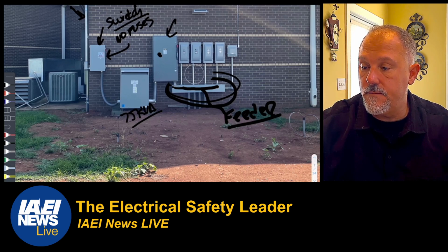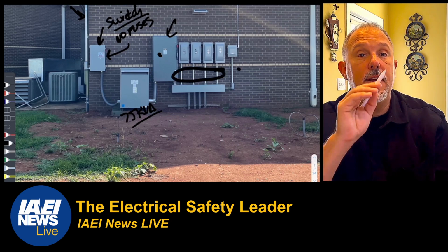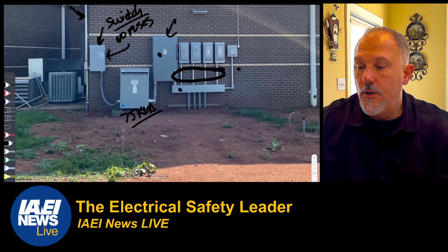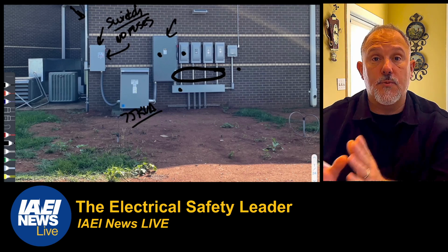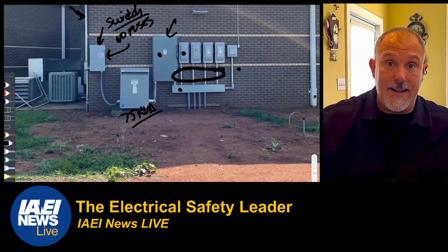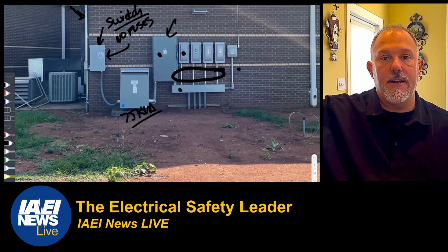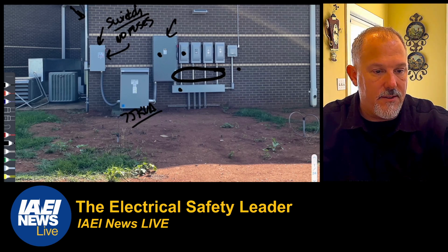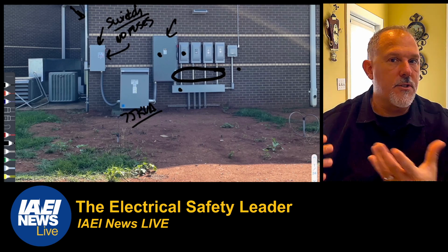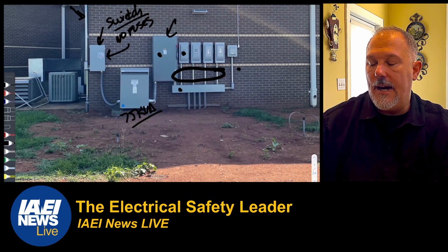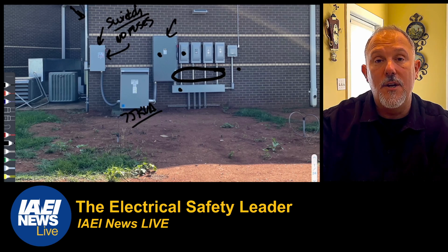The conductors that are in this raceway here, those are taps, and the tap only extends from the gutter to the fuse. And if this was indoors and not external, because we get some forgiveness for external, because it's external to the building, I don't have to worry about causing a fire inside the structure. I am outside of the structure, and I don't have to worry about the combustibles, etc. And it's all enclosed in raceway. So I am following the tap rules for those outside conductors. But if I was inside, then I'd have to provide additional protection.